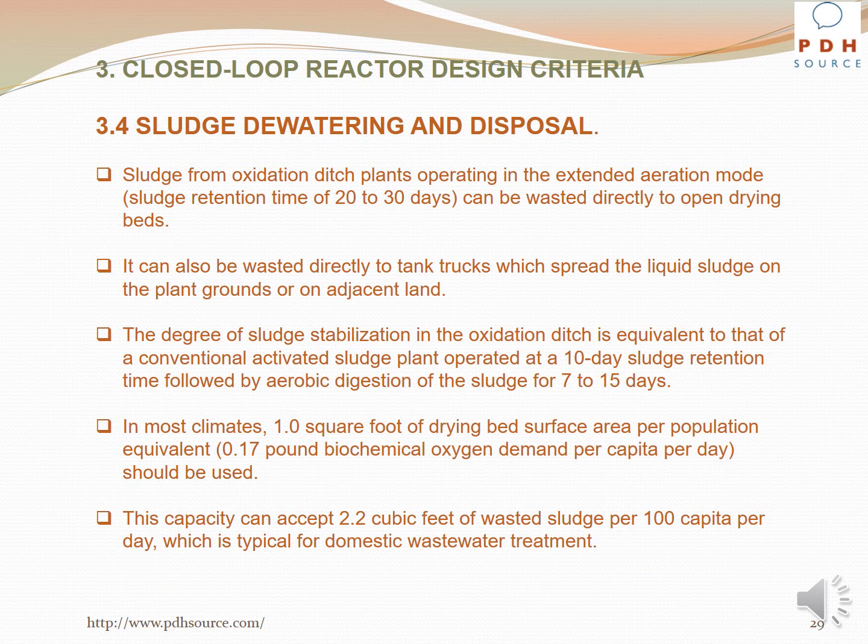With regard to sludge dewatering and disposal in the closed-loop reactor design, sludge from oxidation ditch plants operating in the extended aeration mode with sludge retention times of 20 to 30 days can be wasted directly to open drying beds. It can also be wasted directly to tank trucks which spread the liquid sludge on the plant grounds or on adjacent land. The degree of sludge stabilization in the oxidation ditch is equivalent to that of a conventional activated sludge